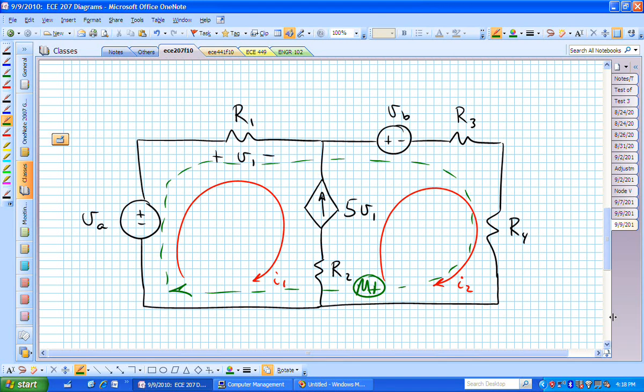Question? So on this example, does the second resistor take effect at all? What is the purpose of R sub 2? Did it enter into any of our equations? Now I have to go back and look. It doesn't, because why? You now have a current source in there that's basically controlling I sub 1 and I sub 2, and R sub 2 is irrelevant.